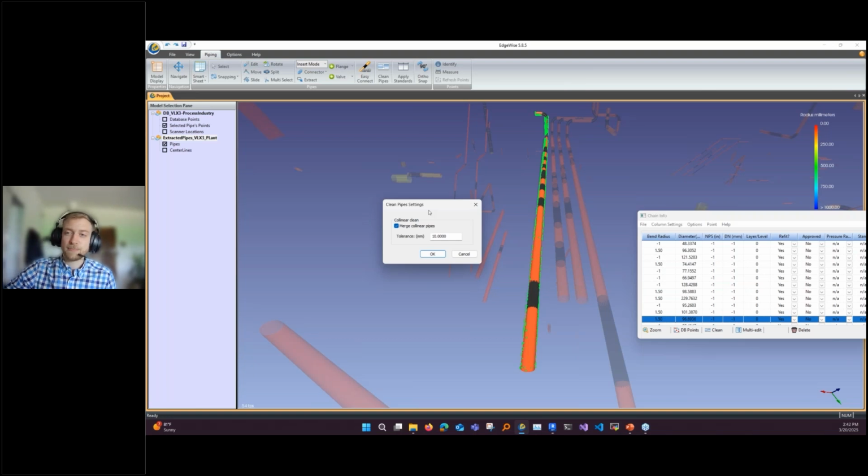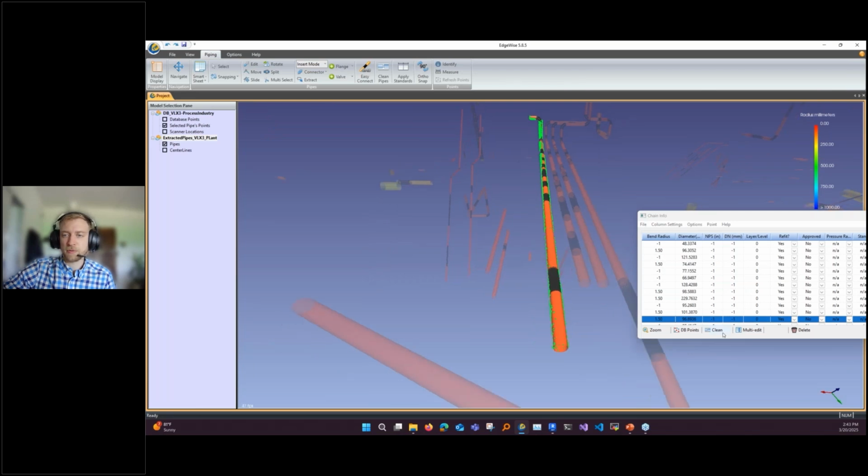If you want a design intent model, where you export straight out to a straight line, then just raise this value up way higher. So if I make this a meter or even 100 millimeters, this will basically make it a straight line. The elbows will still be non-90-degree elbows. We're not completely moving everything around, but it will make connections straight lines. So that's a useful thing if you need to do more of a design intent model. That's a big one.